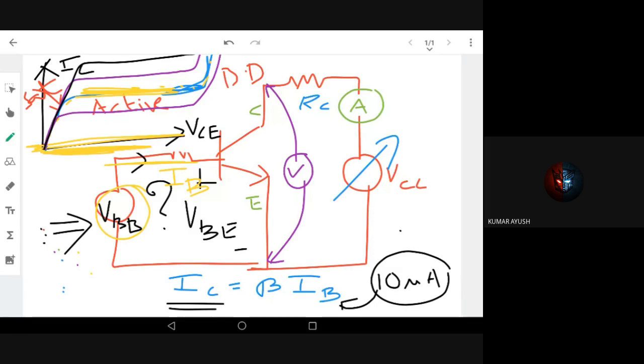But you can see the breakdown region is reducing. That is because more current my transistor is conducting at a higher or the same voltage. That means the power handling is high. The power dissipated by the transistor is high, so it can break down much easier than in lower current regions. So this current is maybe 10 micro, now this is 20 micro, this is 30 micro, this is 40 micro.